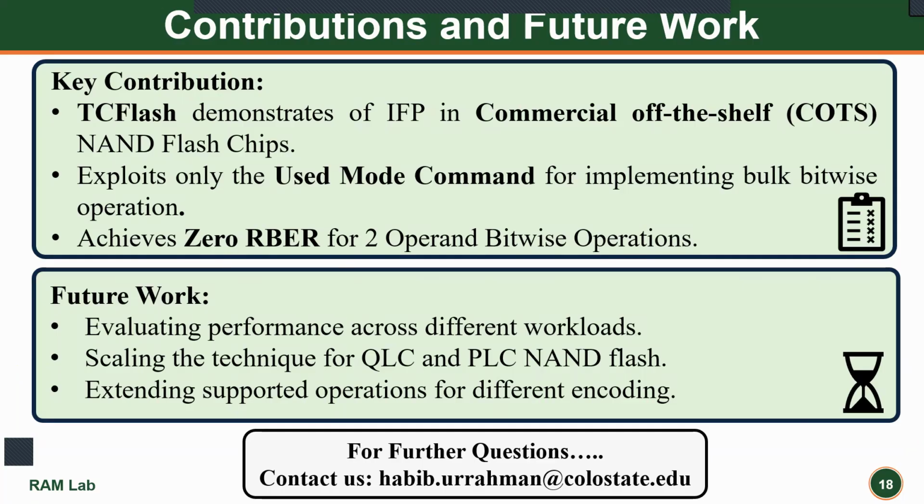Finally, our key contributions are that we have demonstrated the first commercial off-the-shelf chip implementation of in-flash processing. We have only used user-mode commands and achieved zero raw bit errors for 2-operand bitwise operations. In our future work, we want to evaluate the performance across different workloads, scale our scheme to QLC and PLC NAND flash memory, and extend the support for different encodings. Thank you all.